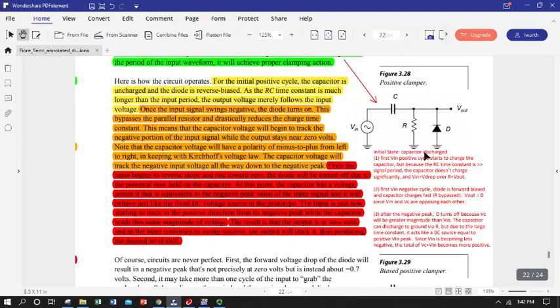So if you want to go through that on your own, I've put the stages again in terms of what happens with each waveform, but I basically just talk through that. Forward cycle, not much current is flowing, we have a huge resistor, big time constant, no charge accumulation, and the output voltage is basically just going to track the input.